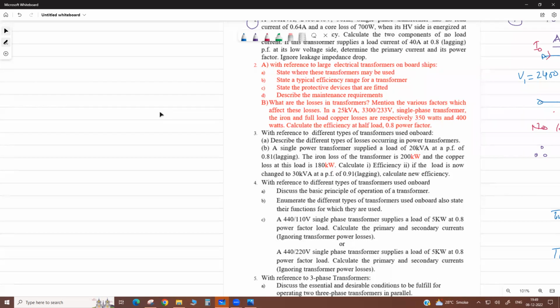Then we check other parameters, like the temperature. We continuously monitor the temperature of the winding because it is directly proportional to your load or overload. Okay, now under voltage, short circuit, overload, these are the protections we have provided for that. So maintenance is this, okay, please check.